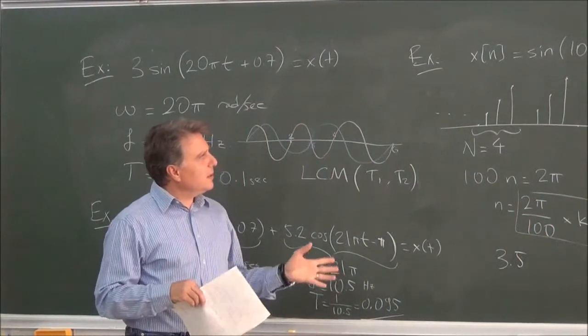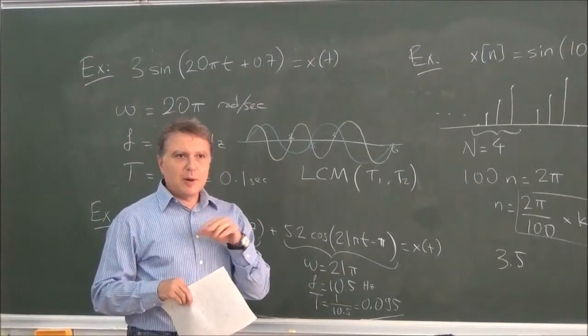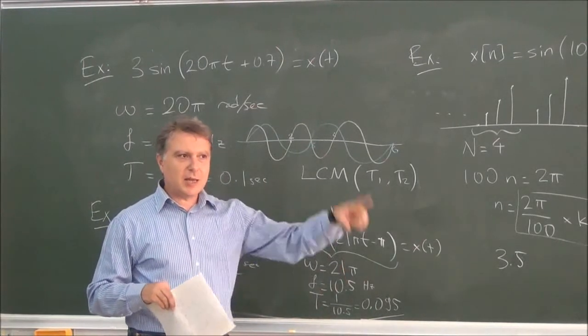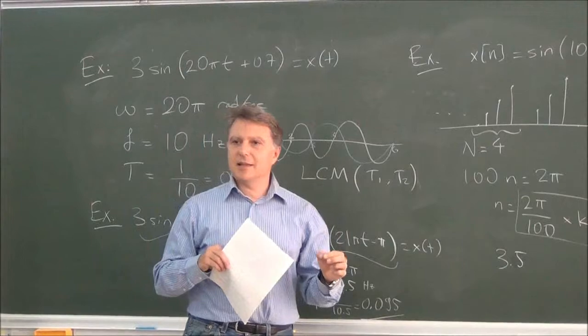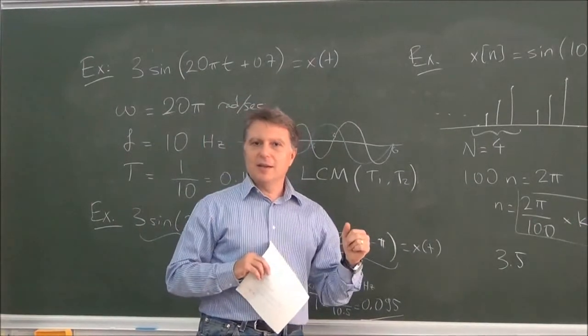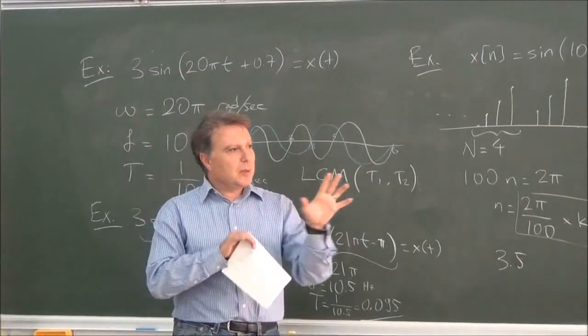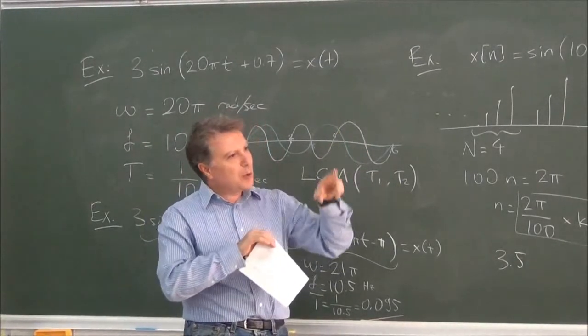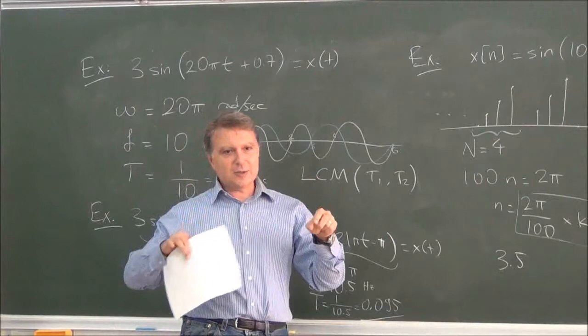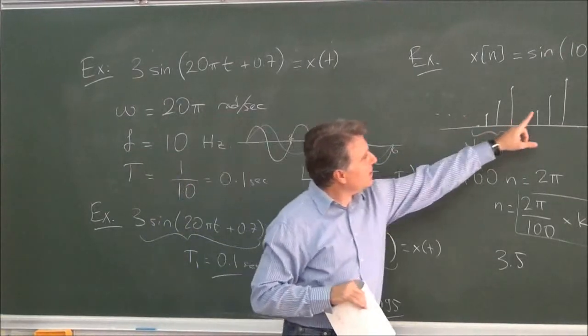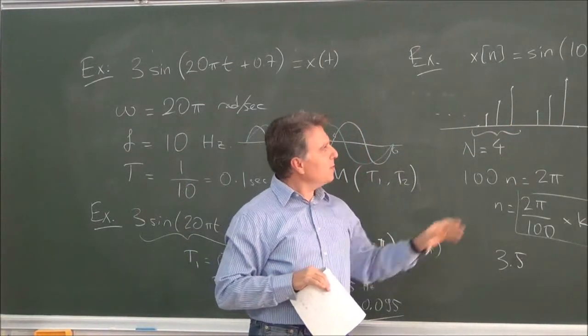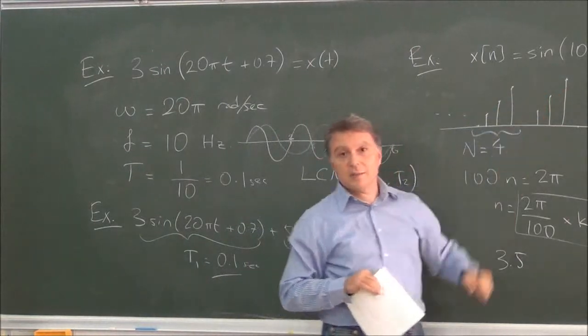You will see that it looks like a periodic signal, but that periodic-looking shape is not precisely repeating itself. Within a period, it looks the same as within another period, but they are not exactly the same. Only the envelope shape is like a sinusoid, but the discrete values are not repeating precisely. Therefore, you must say that this one is not periodic.